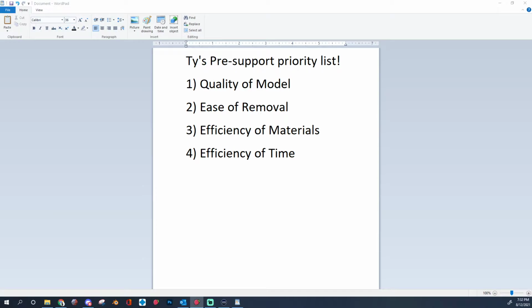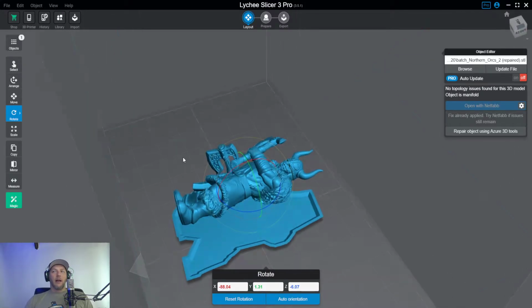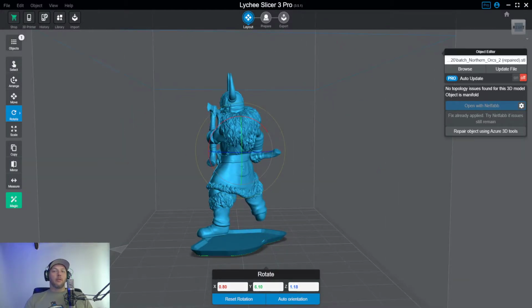So it lasts about 2,000 hours, but it adds up over time, especially if you're doing production or you plan on doing production. Like if you have 20 printers going, and we could possibly have, this is not what you would want to do, an estimated printing time of 3.5 hours to get this model out. But otherwise, you would have 2 hours across 20 printers. I'm sorry, 5.5, you'd have a 2-hour difference. Across 20 printers, that's a 40-hour difference use on your hardware.